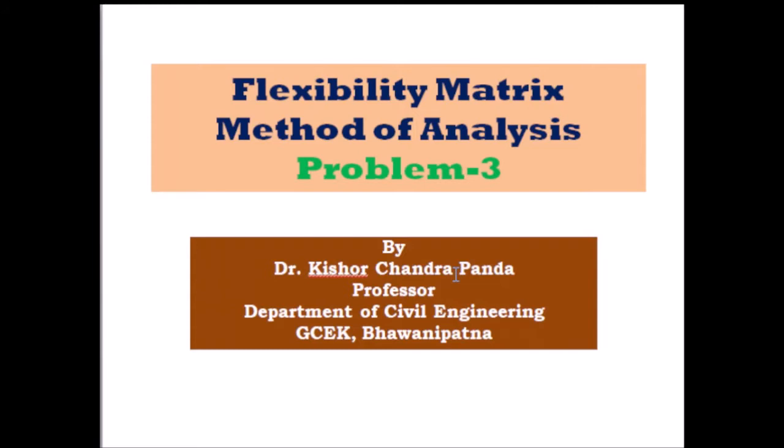Let us take a one-dimensional spring. One end of the spring is fixed and the other end of the spring is free. If you apply a force P1 at the free end, what will happen? The flexibility of a spring is defined as the displacement delta 11 at the coordinate 1 due to unit force at the coordinate 1. So if you apply a unit force at the coordinate 1, whatever displacement takes place due to that unit force is called the flexibility at the coordinate 1, delta 11.